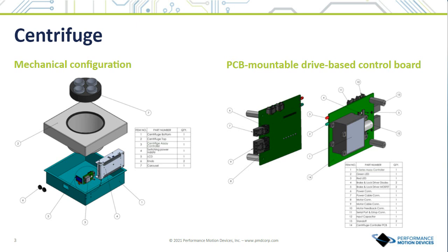And the carrier card that you put in is a dumb 2-layer card, and all you're doing is customizing the connections. So all the smarts are in the drive. You pick your host interface and your power connections for the motor, and you can put in the connectors, and this lets you customize it quickly and get to an end market faster.